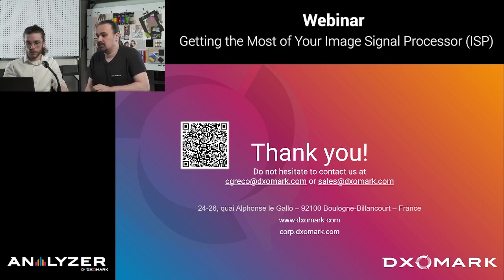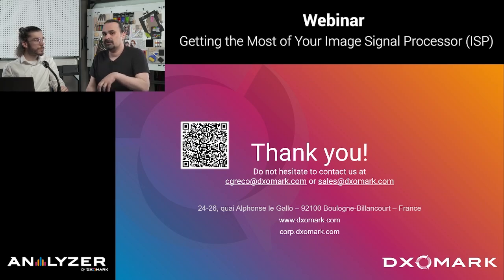For instance, you might not need color at all in an ADAS application, but you might want more contrast, and it doesn't need to be realistic, okay? Because you are not looking at the image to see how nice it is, you are looking through your windshield, right? So what you want is something that enhances your human vision, and specifically I can run an algorithm on it. So maybe in a case like that, my handling of contrast would be very different, because I don't want something where I can recognize the features of a person. I don't care who is crossing the road. I just want to know that somebody's crossing the road.